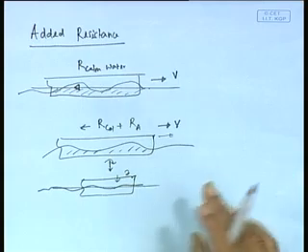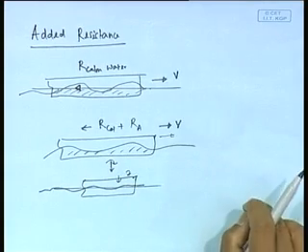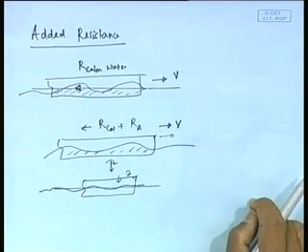this resistance originates from the fact that the ship is creating waves because of its wave induced motion in the first place, because it is undergoing some oscillation. So, therefore, this resistance formula that we will find out will be all connected to heave and pitch and other modes of motion. Okay. So, now the question is that